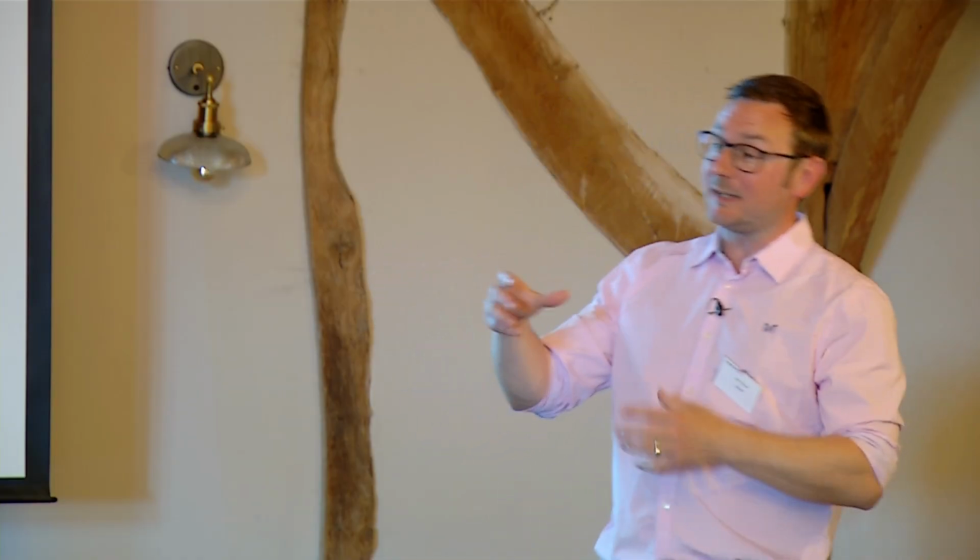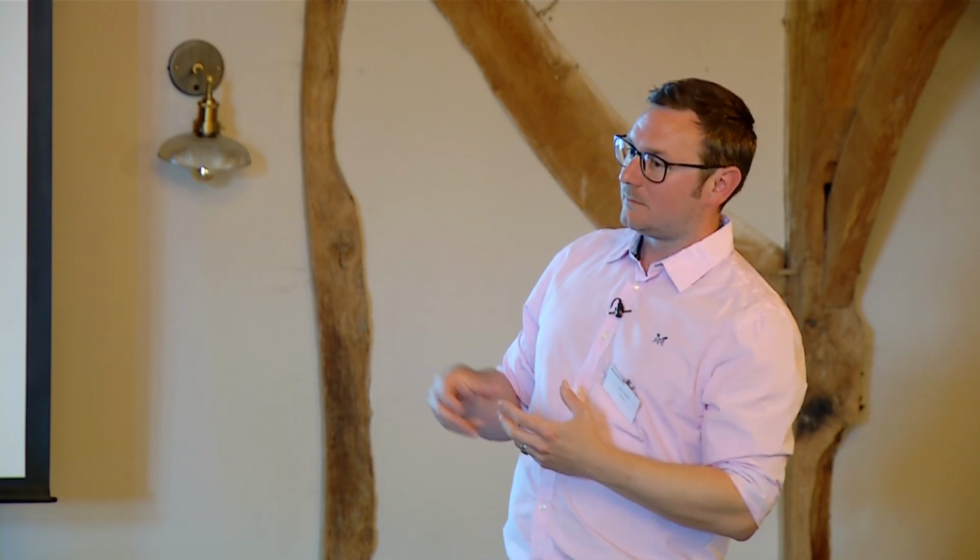The difficulty that you have is that first floor, what it's used for. It's too small for a bedroom. So the problem is that when you make an assessment of an application in place for your drawings, if that first floor could be utilised as a habitable space, even if it's a desk or they're getting overcrowded and somebody has another child or whatever, and then it's a cot that's going in there, then you have a significant impact because the second floor becomes an inner room.